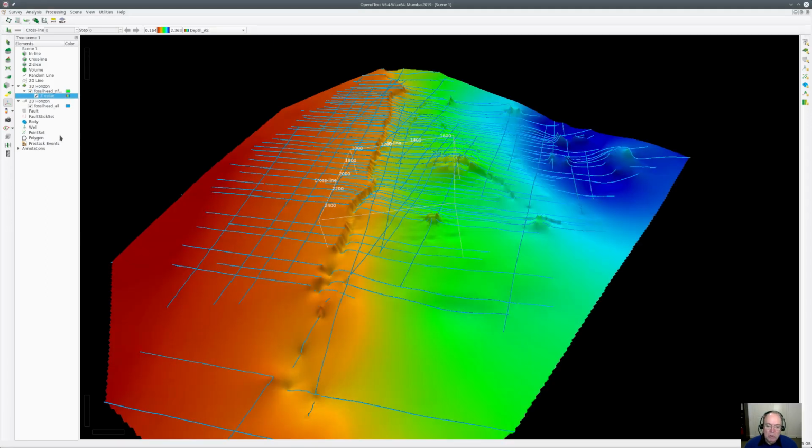Generally, I draw the fault constraints by hand, but wmPlugins includes an experimental tool to generate fault polylines at the intersection of a 3D horizon and fault surfaces if you have them. It is a two-step process. Firstly, generate a continuous horizon using the multi-level B-spline algorithm.